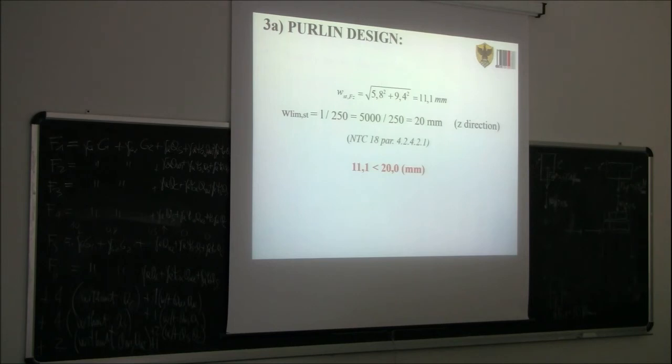Either you round it before and say, okay, I found 120 and this 120 is not greater than 120, but you can't write in your design report 123 as the design demand, which is more or less 120, so it does not exceed the limit of 120. Because if one day, by chance, the structure should collapse, you could suffer some problems. Okay? Because formally you didn't satisfy it, because 123 is greater than 120.